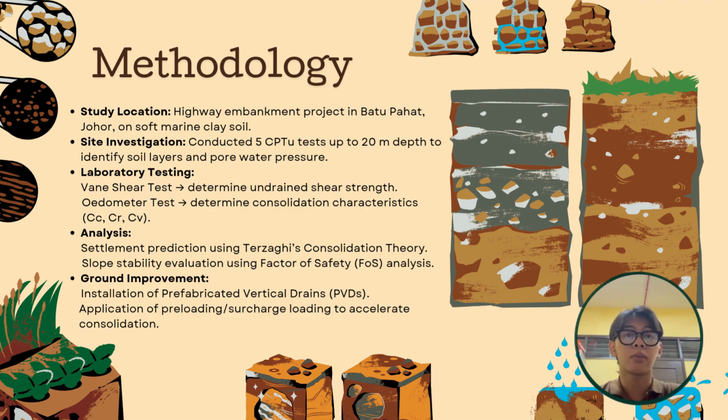The next is laboratory testing. Laboratory tests were conducted to determine the properties of the soft clay. Vane shear tests measured undrained shear strength, while oedometer tests provide consolidation parameters.